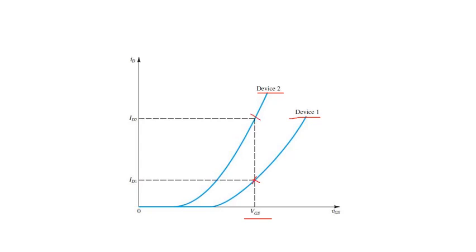This variation is mainly because of the threshold voltage Vt, mu n, oxide capacitance Cox, W by L ratio. They all vary even when VGS is constant, and you get the characteristics in this particular manner. So here you can see large variation in the ID current. So ID varies, it is not stable. Hence, this method of biasing is not an appropriate method.